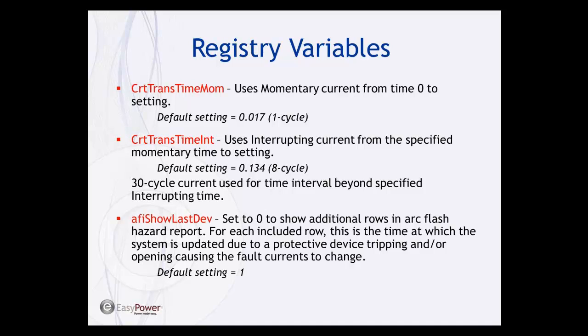I do have one additional thing on that: if you are printing EasyPower labels from that, do check your label before you print it out to make sure that the result is accurate. Because we have the separate rows, you want to make sure that you're getting the row that you want. That's why it's not a default setting.